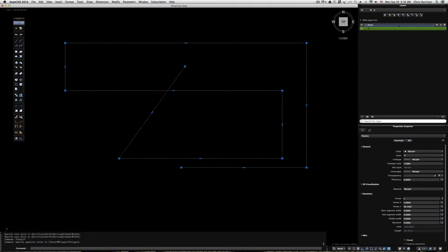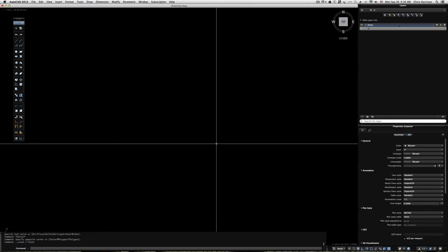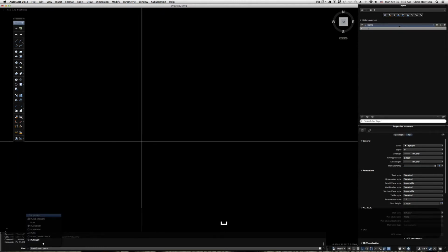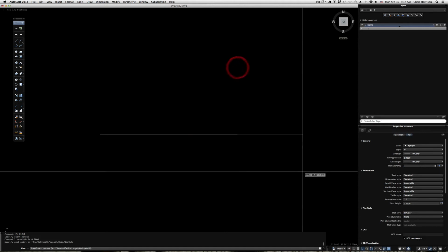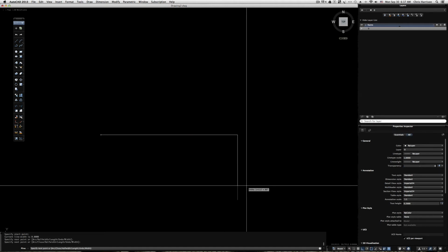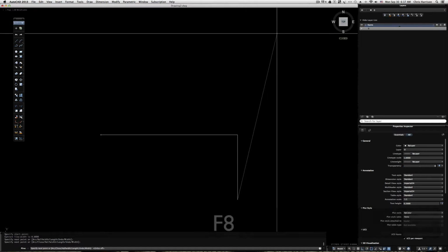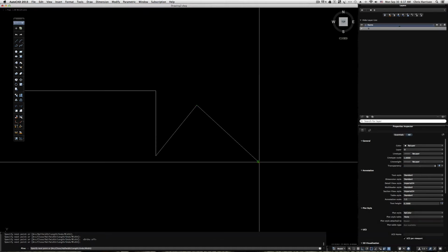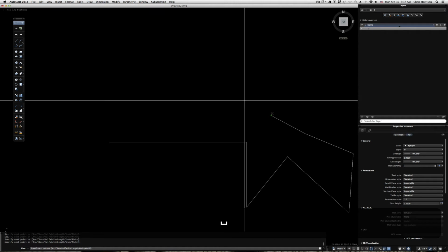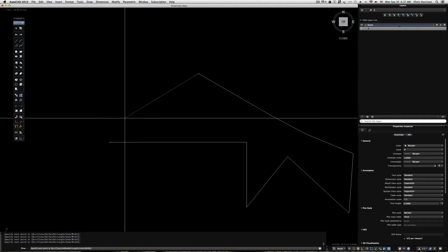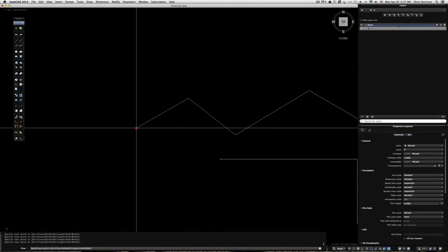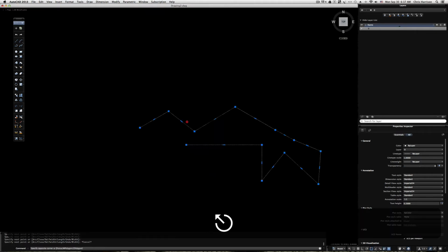There's that. That's good to know about. And you want to toggle these things on and off. So once you've set it, if you try to go in again with the Polyline tool, you see that I'm still on ortho. And to turn off ortho, you simply would hit your F8 again. I'm doing the function F8 to allow you to transition back to your normal line or Polyline tool at any angle that you select. Okay.